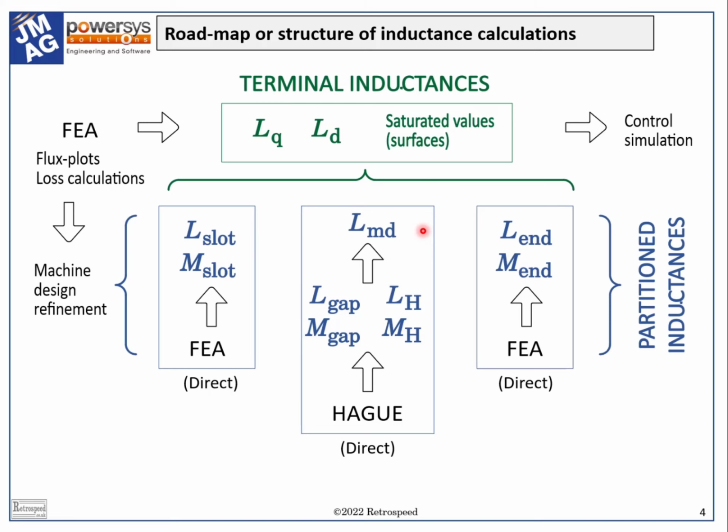The modern finite element process computes and displays the magnetic field in the machine in far more detail than in the separate component calculations. These component calculations are all based on quite severe idealizing assumptions which barely satisfy the fundamental field equations and which approximate the geometric shapes and simplify the BH characteristic properties of the steel.